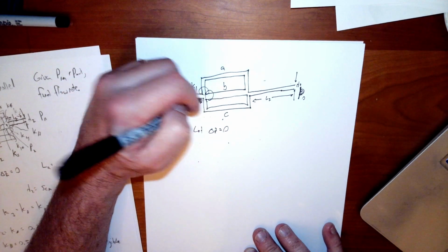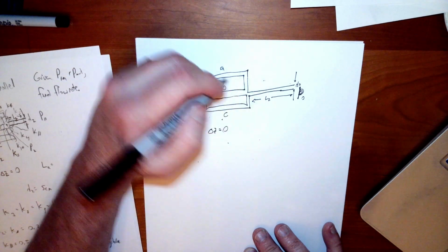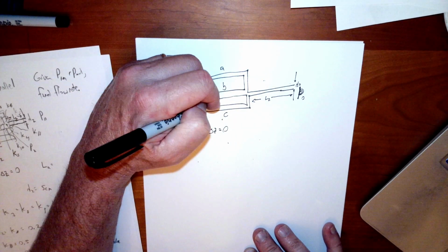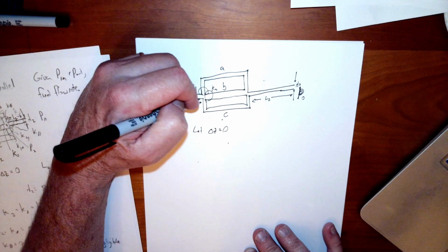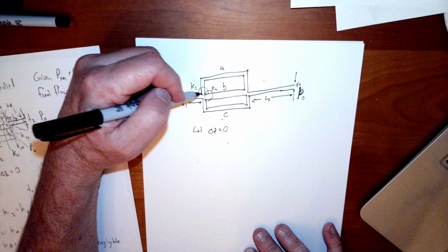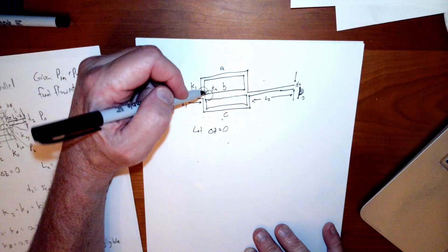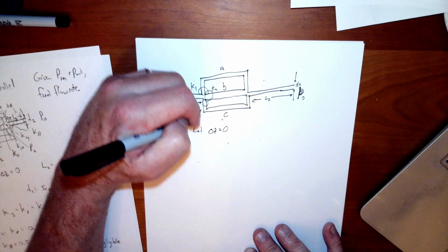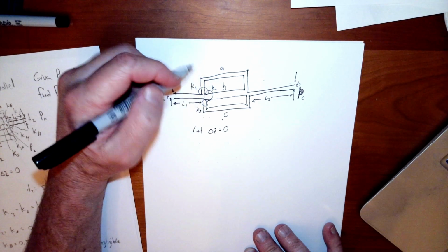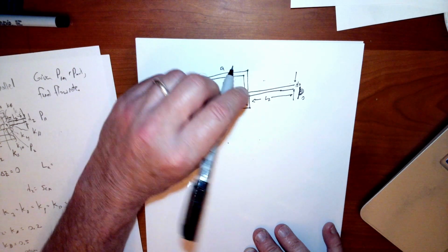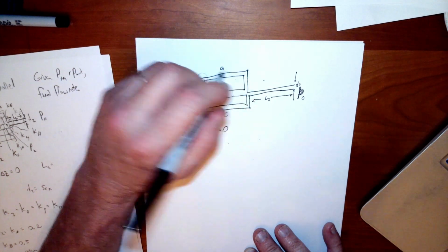Similarly, there's a loss coefficient there, which I'm going to call K2. This is the loss coefficient for the fluid that goes straight through the junction, but nonetheless there will be a loss coefficient, because there could be recirculation zones as it goes through these cross channels. We're going to have K3, of course, for the fluid that comes down here and goes downward in that junction. Of course, we're going to have all these corners.